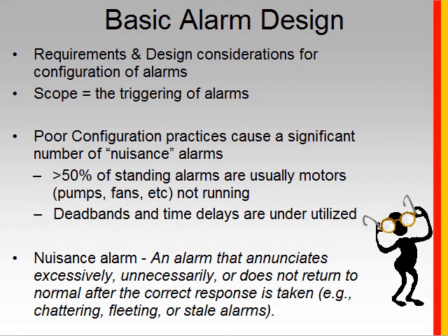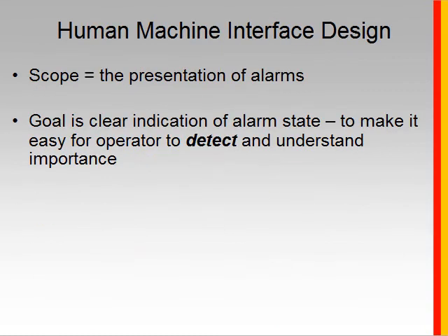In some cases, they found up to 90% of the alarm load to the operator was reduced just by addressing or properly setting these deadband parameters. So it's a very important part of the alarm life cycle.